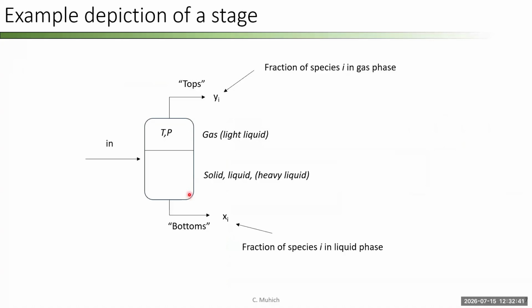So we can take an example of what one of these stages looks like. So maybe this is a distillation column. I'm going to draw this in an engineering diagram type style so you get used to looking at this. These diagrams, right, we showed in black boxes last time, but we can start putting symbols in there that will correspond to engineering practices. So here we have our flow in. We have this sort of square looking thing. This is going to represent maybe a flash stage. Don't worry about what flashing means, but we'll talk about that in a second.